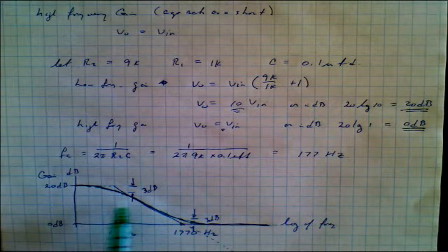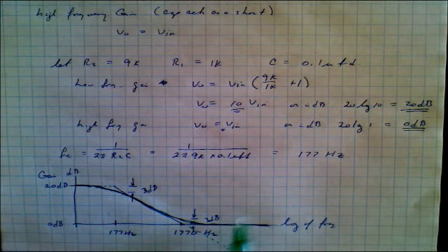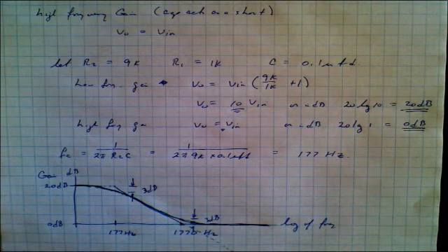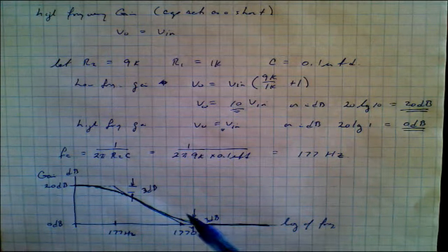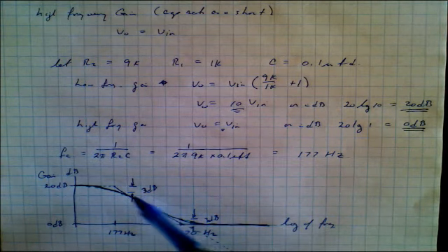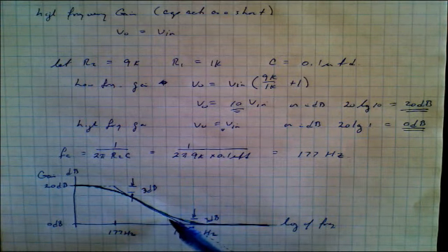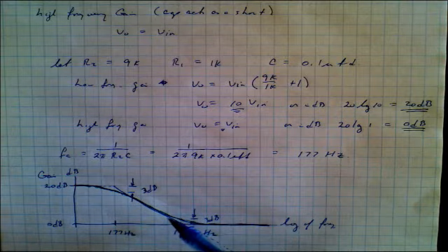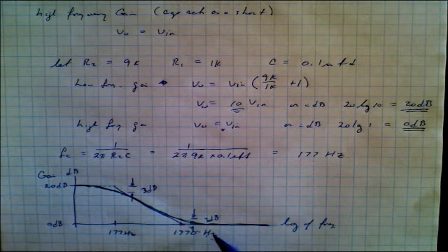So you can see why it's called low pass, because it's passing only low frequencies and it's attenuating high frequencies. Notice also that this is the low pass response for a non-inverting amplifier, whereas for an inverting amplifier, it falls off like this.